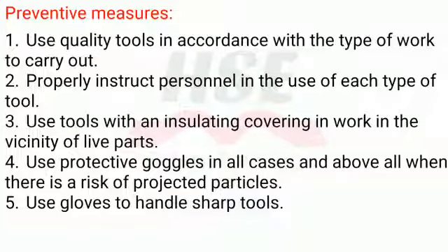Preventive measures. 1. Use quality tools in accordance with the type of work to carry out. 2. Properly instruct personnel in the use of each type of tool. 3. Use tools with an insulating covering in work in the vicinity of live parts. 4. Use protective goggles in all cases and above all when there is a risk of projected particles.